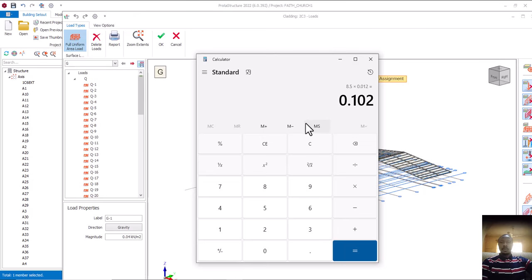Now don't also forget that we have a suspended metal frame, in terms of channels or hangers, screws and all of that. Based on all these hangers and screws, they have their weight. The weight is between 0.03 to 0.05 kilonewton per meter square. Are we together now? So if you are taking the average of this, what they have given to us as the screw values, hangers, all those accessories and all of that.